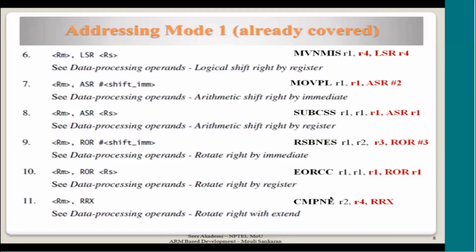So you can put any condition, but the S is not appearing here because it is default. This compare instruction always affects the flags. So even if you put yes or no, it doesn't matter. The compare instruction will always be affecting the flags. So this summarizes addressing mode 1.